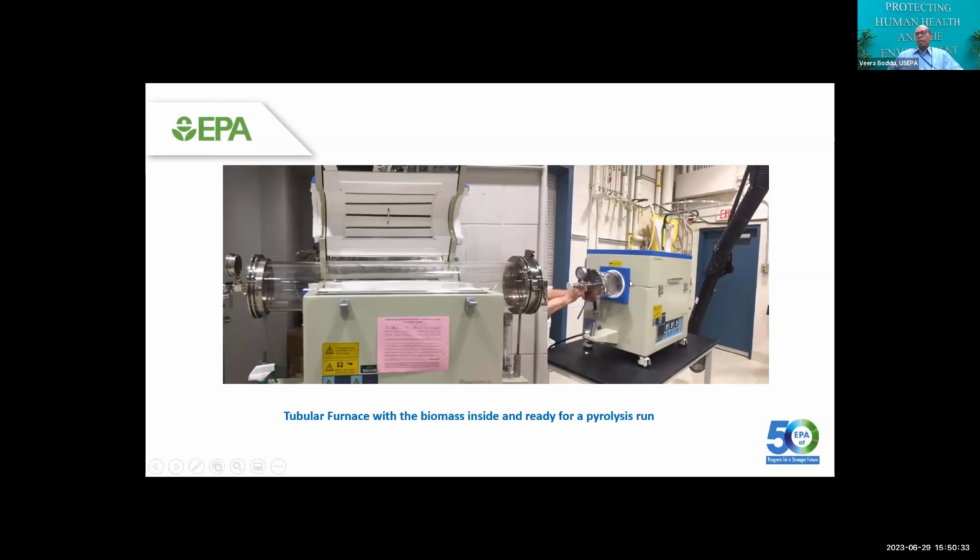And at the peak temperature, either 500 or 700 degrees Celsius, we used about an hour of dwell time. Once the heating and pyrolysis profile is over, we let it cool overnight under a nitrogen environment. It is very important: if you try to take it out without cooling, everything turns into ash. So don't open the reactor until it is cool, near room temperature.